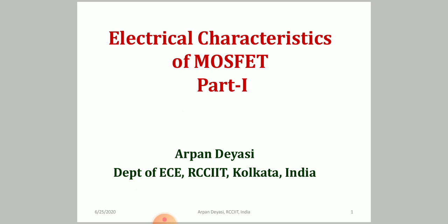And then I proceeded towards the MOSFET. At the beginning, I mentioned that MOS and MOSFET are not the same. Though they may look the same, they are not. People confuse the terms because the first three letters are the same, but they are different. MOSFET is a 4-terminal device, which is a transistor, and MOS is a 2-terminal device, which is a capacitor.